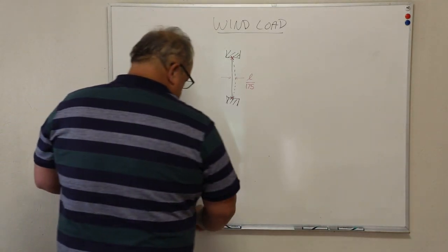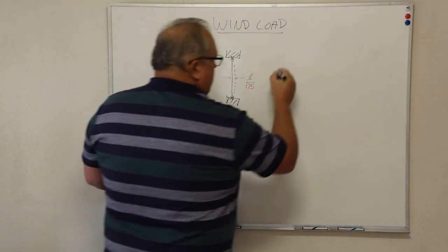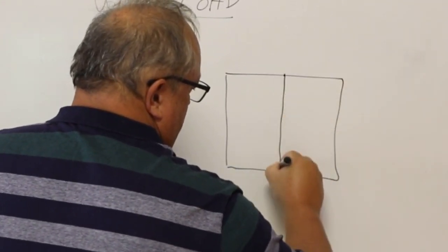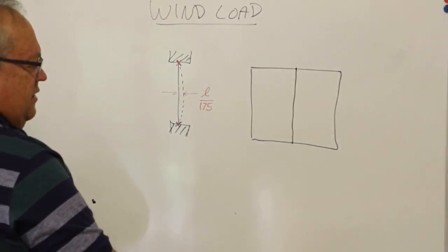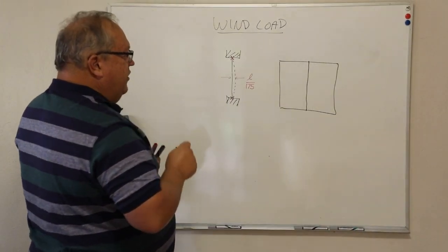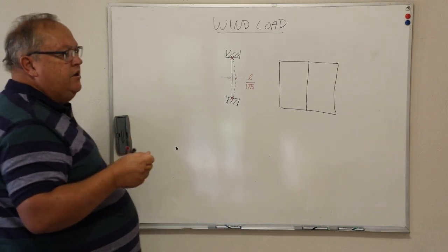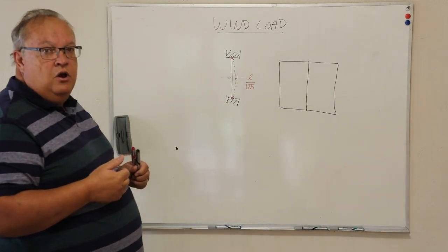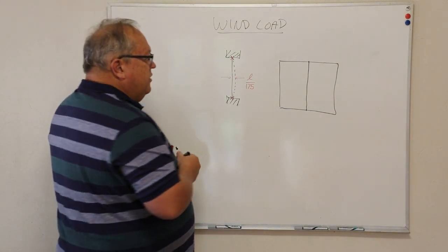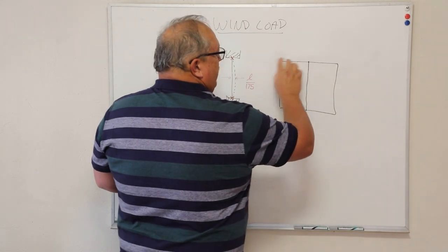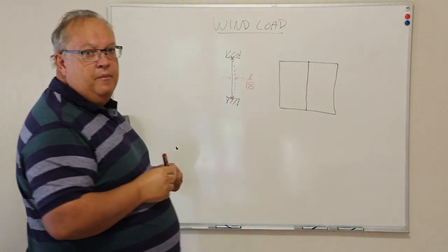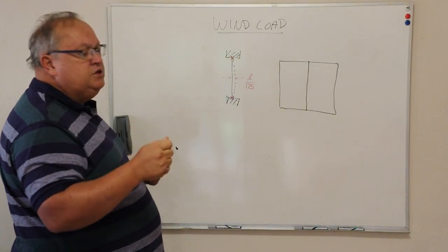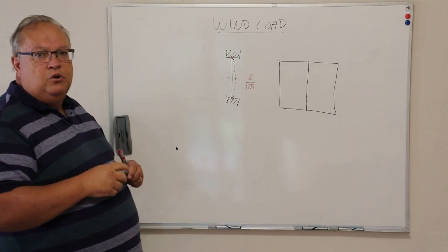Let's look again quickly at that outer frame and say, why are we only considering the mullion in this situation? There's my elevation view, and a very important criteria in this industry is you as an aluminium manufacturer are allowed to assume that as long as you fix your frame correctly to the structure around your frame, that structure you are attaching to is strong enough to support the wind load.